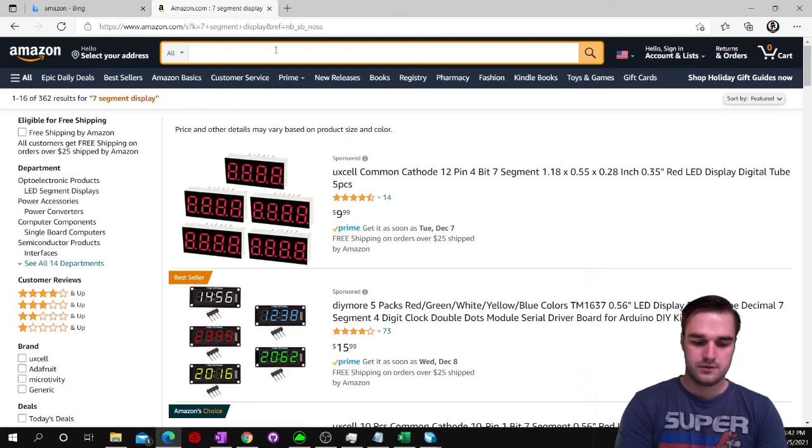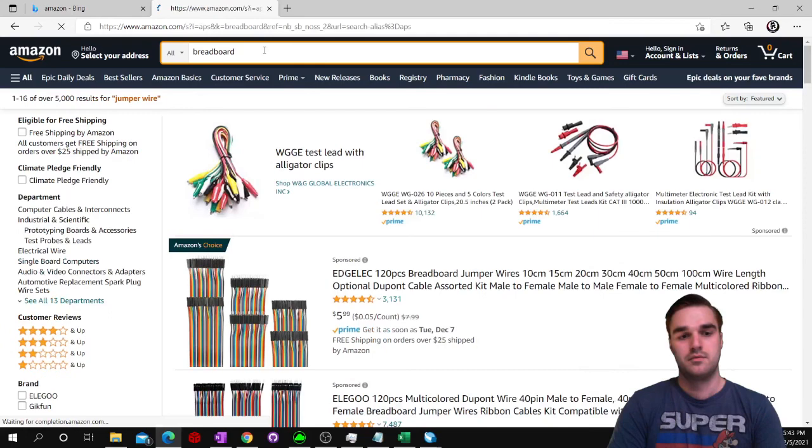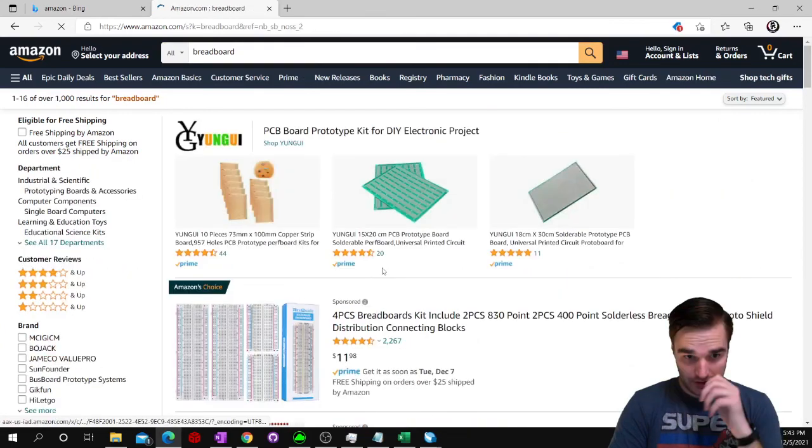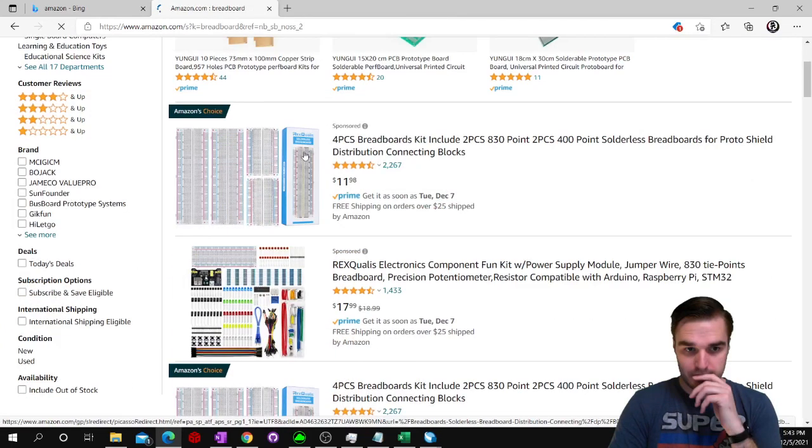And you need a breadboard. All of these components are very, very cheap. Breadboard, any will do. And we're going to need a resistor set. I forget the exact size of the resistor. I think probably 220 ohm will work, or 330 ohm, something like that. But get something like this for your collection.